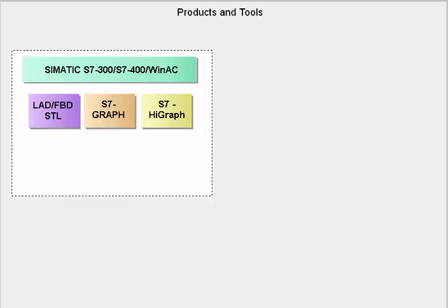The Simatic languages S7 Graph and S7 HiGraph support process diagnostics anyway. In other words, they provide the option of programming the relevant monitoring conditions directly next to the program logic in the sequencer and status graphs.